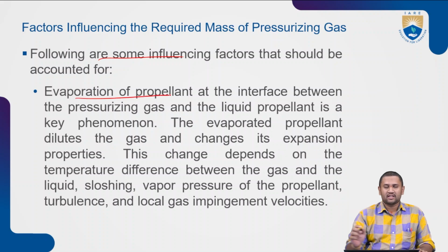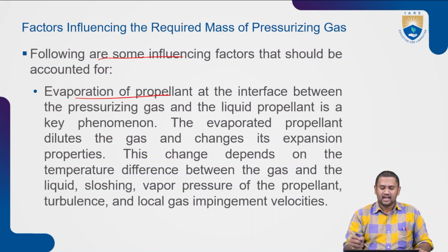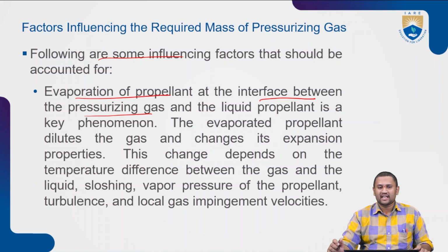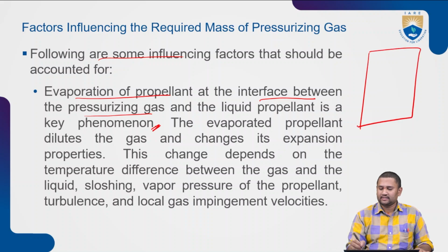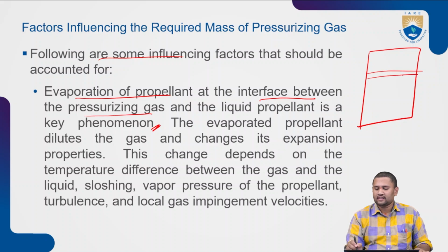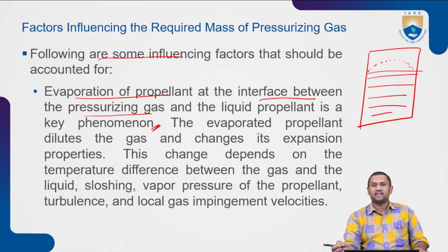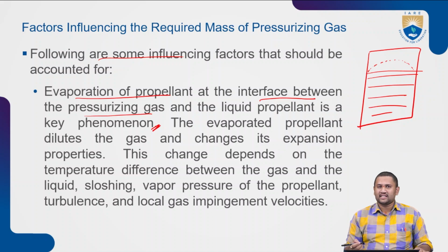The first one is the evaporation of the propellant, and the interface between the pressurizing gas as well as the liquid propellant is a key phenomenon. What do you mean by that? Basically, in any liquid propellant tank, which we will be filling, it contains some amount of propellant, and the liquid propellant itself will tend to evaporate, right? Evaporate either due to its condensing nature or due to the temperatures at which it is being kept, particularly the ambient temperatures.